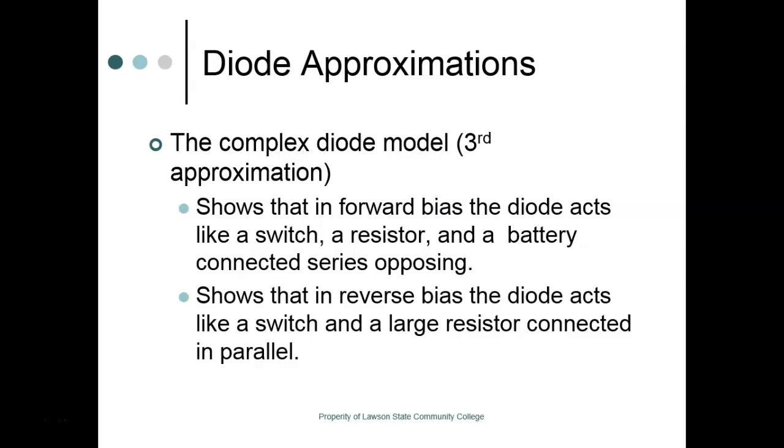I think for ours, these are 1 amp diodes. The little black ones that we'll be using are 1 amp. And it says they drop around, I forgot, 500 millivolts at the barrier and around 1.1 volt with 1 amp flowing through it. But 1.1 volt and 700 millivolts is basically not much to worry about, right? You understand that? What about 400 millivolts difference?